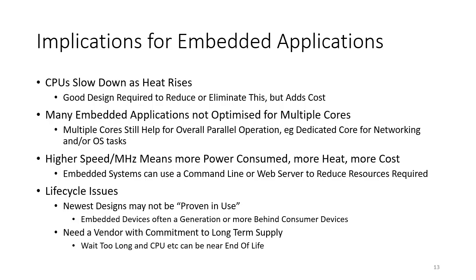But if you're in an industrial application, you might be looking at something that's maybe 2 generations behind, and that's fine. One of the great things about these industrial versions of these chips is they do have a longer life. Of course, the vendor themselves will take a lot of care to make sure that these chips are capable of operating correctly. But what it does mean is that typically, if you're looking for an industrialized device, it won't be the very, very latest generation. It will be 1 or 2 generations behind. And that's fine, because if you were using the latest generation, you might find there are unfound bugs yet. You might find there are cybersecurity issues. You might find other issues. If a chip is a couple of years old, then it's likely that those sorts of issues will already have been found.